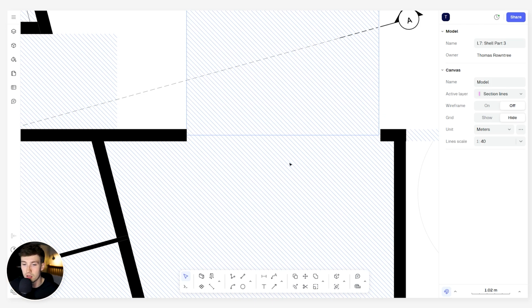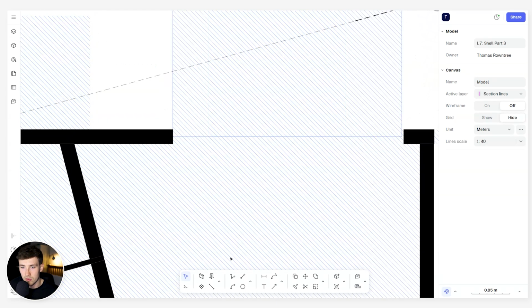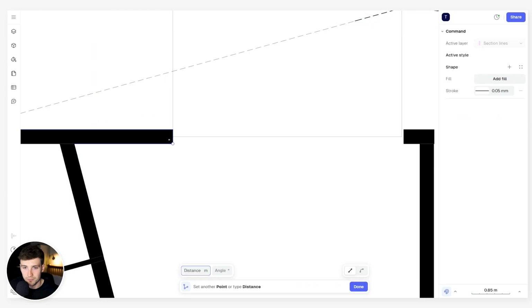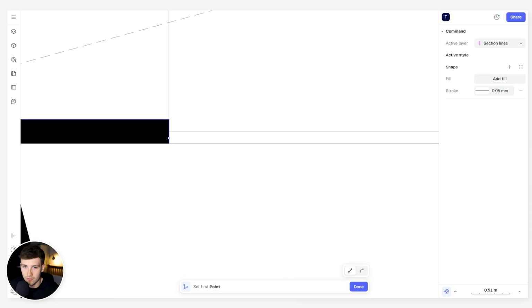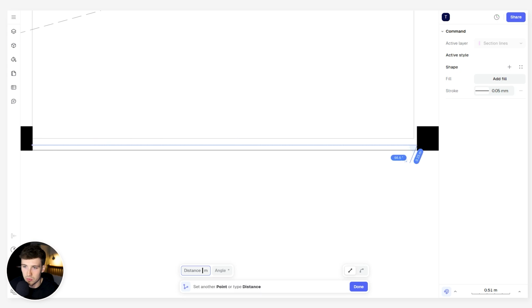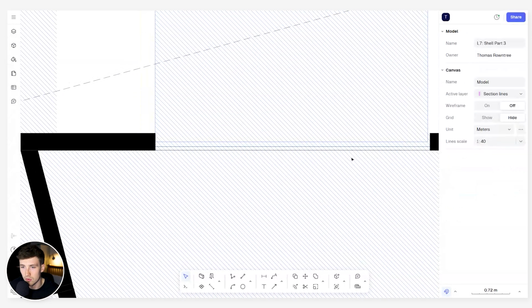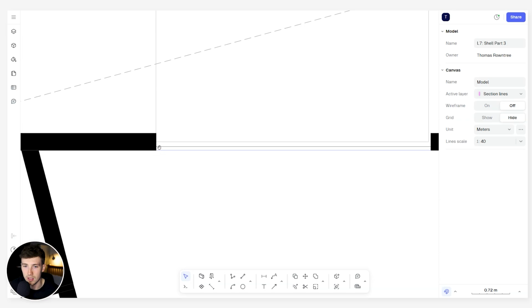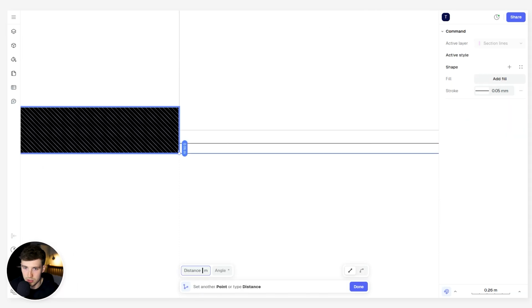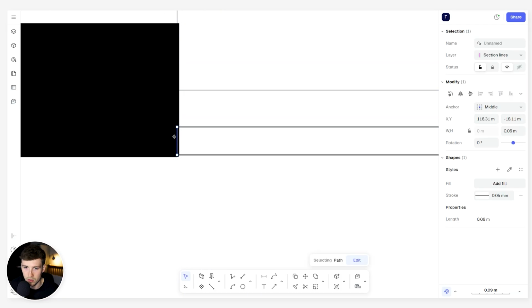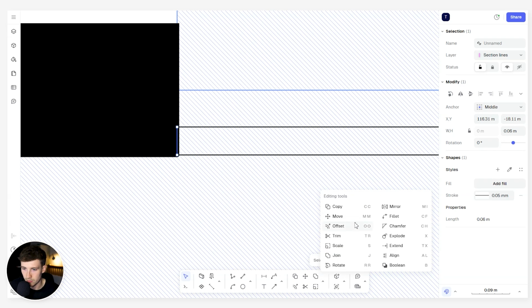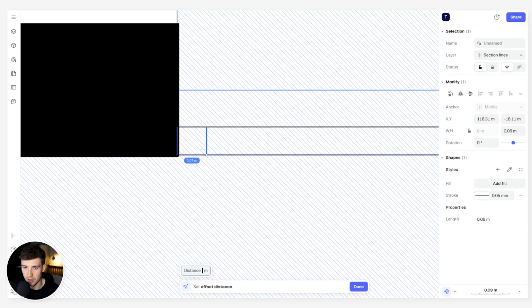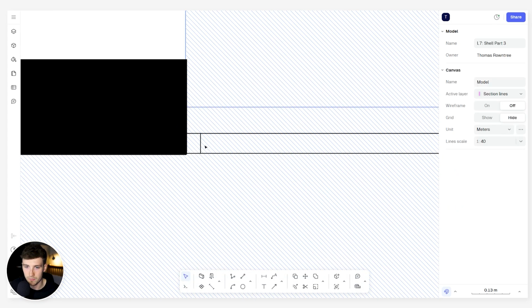Additionally, if you couldn't find a block that you wanted to implement into the drawing and you wanted to create your own, you can do so. So one thing that I'm going to draw here is for this garage door, we could very simply use the polyline and create some kind of indication of a potential, I don't know, shutter or door that's going to come down and land into place. We can add a bit more detail to it to show that there's going to be some kind of edge to it. We can then offset that edge by heading down into here and offset that by, I don't know, let's say we'd have a 50 mil edge.